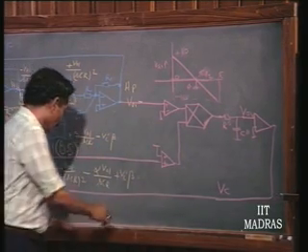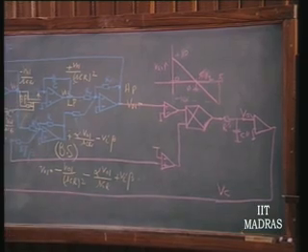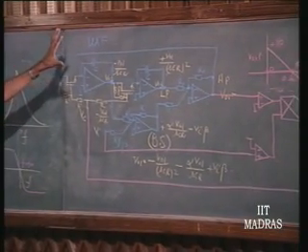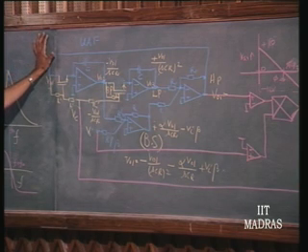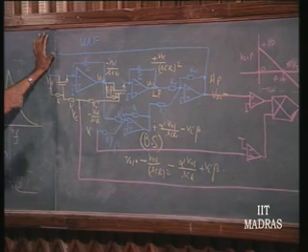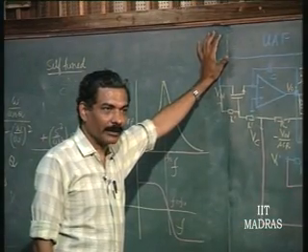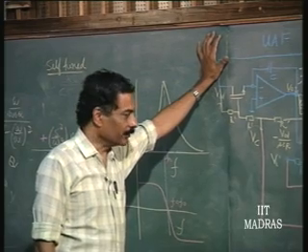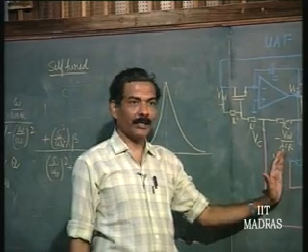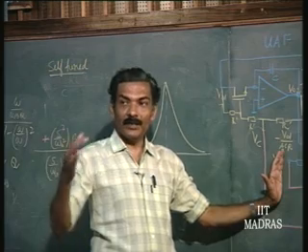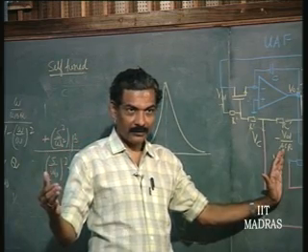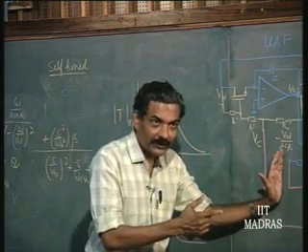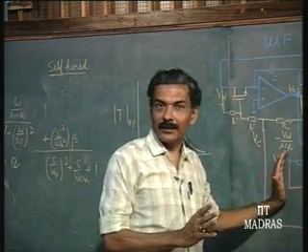Now, I would like you to go through this entire scheme. We will do it once again later and make sure that this particular scheme functions as a negative feedback structure. What does it mean? When this is at omega equal to omega r, if the original frequency to which it was tuned was less than omega r, now the feedback should be such that it should be brought towards omega r, that is a negative feedback system.